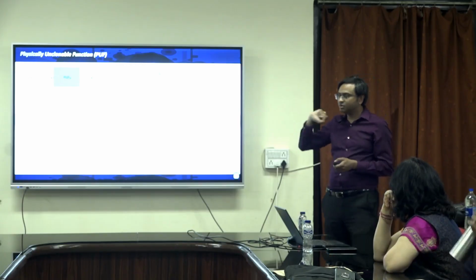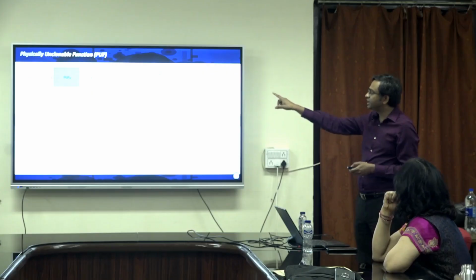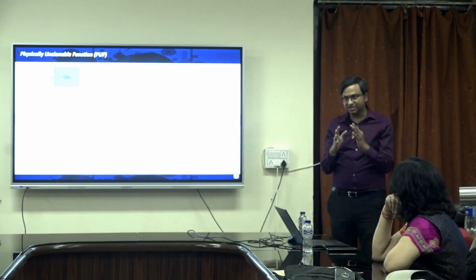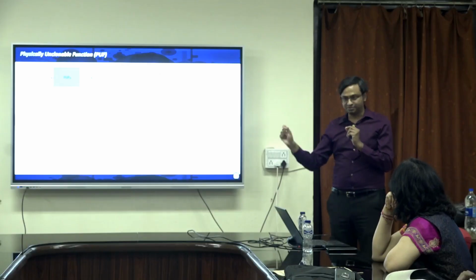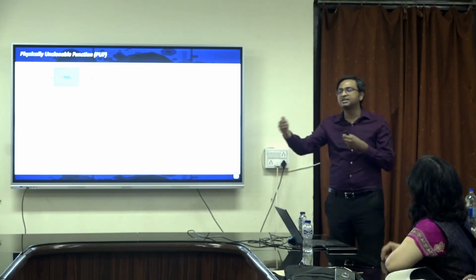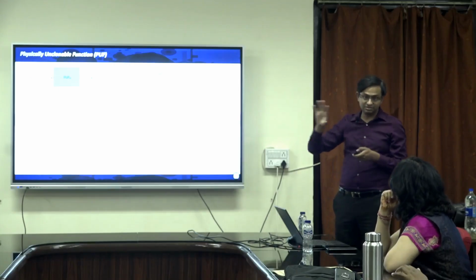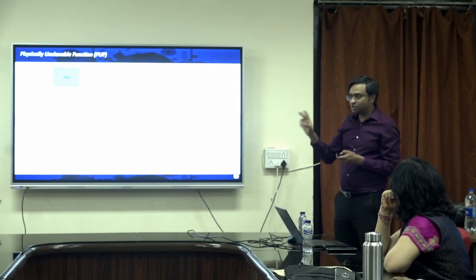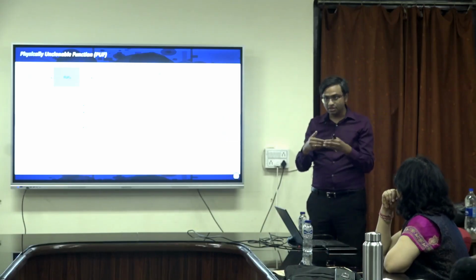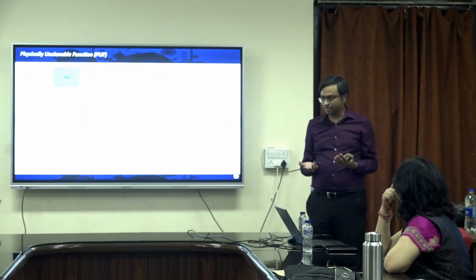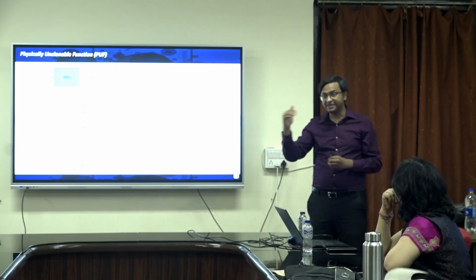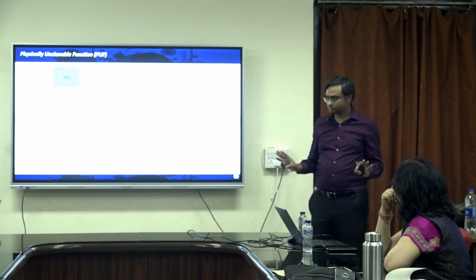And then it's a function because it is based on some math, but you see we call it a challenge-response pair. So the PUF is a physical medium. It could be anything, and I will give you some examples of that. It's a physical medium to which you put a challenge, and it gives you a response. So there is an input and there is an output. The input is your challenge. You're challenging that physical medium, and it is giving a response. This challenge-response pair constructs this physically unclonable function. There are two criteria that this physically unclonable function has to satisfy. If you give the same challenge to different PUFs, the response should be different. And the other one is that if you give different challenges to the same PUF, the response should also be different. These are the two criteria.